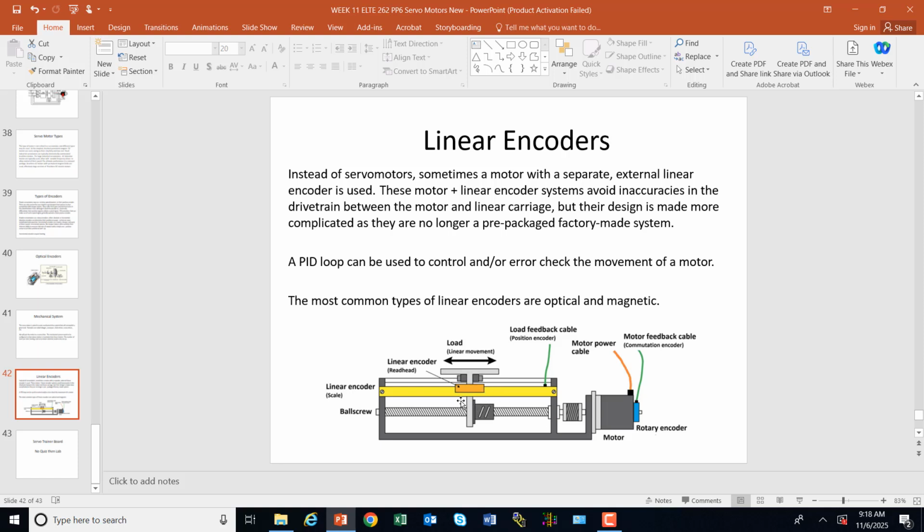And then, like I talked about with the stepper motor, you can put in a feedback control loop here, maybe a PID, to govern this, to be sure that this thing is really working exactly like I want it to. Especially if you're getting some variable torque on here, this motor, because it's got the encoder, is still going to compensate for that variable torque, or at least try to, right? But if you put a linear encoder on there, pushing it back to the PLC, then you can be sure that you're getting your feedback, you're getting your monitoring. It is doing what it says that it's doing.